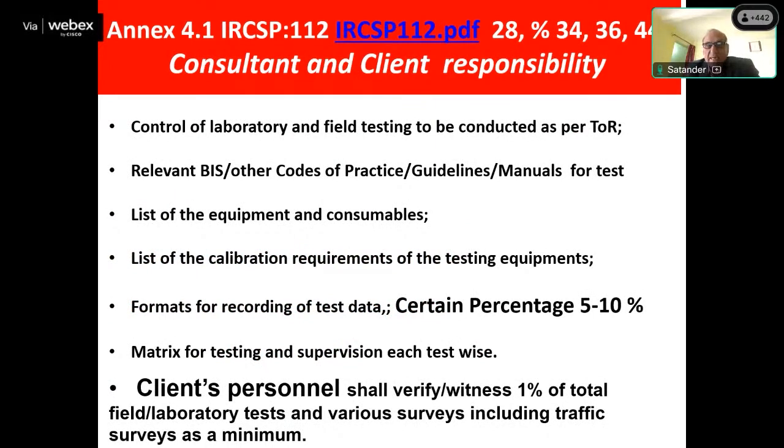What are the duties of the client? What is the duty of the consultant? In short, I have written here, the client must check 1% of the total work. It is written in IRC SP 112, pages 28 to 34. These are the pages where it is written. And the consultant should check a minimum of 5 to 10%. Matrix for testing supervision is test.